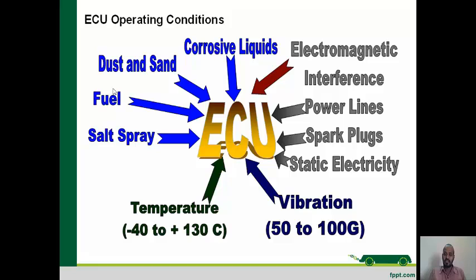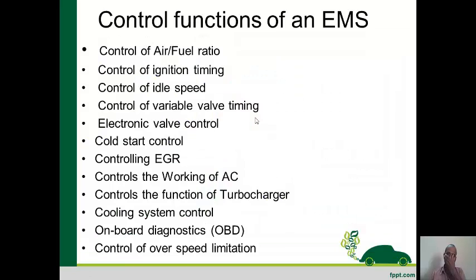If you are mounting the ECU in the engine compartment or directly over the engine, a lot of things need to be taken care of, like salt spray, fuel spray, corrosive liquids, temperature, and vibration. These are all parameters that need to be considered while developing an ECU.